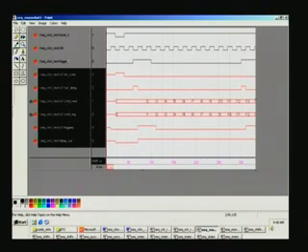and whatever is the current trigger value will be pushed as the previous trigger value for further processing, namely to find the rising edge of this trigger. That is the reason why we preserve this. We preserve the current value of the trigger and then use it in the next clock cycle. Is that clear? That's how you sense the rising edge. And if you see here the run delay, for the time being I'll just say it is counting 1, 2, 3, 4, 5, 6 and so on, right? Not much information here, and we'll come back here also.